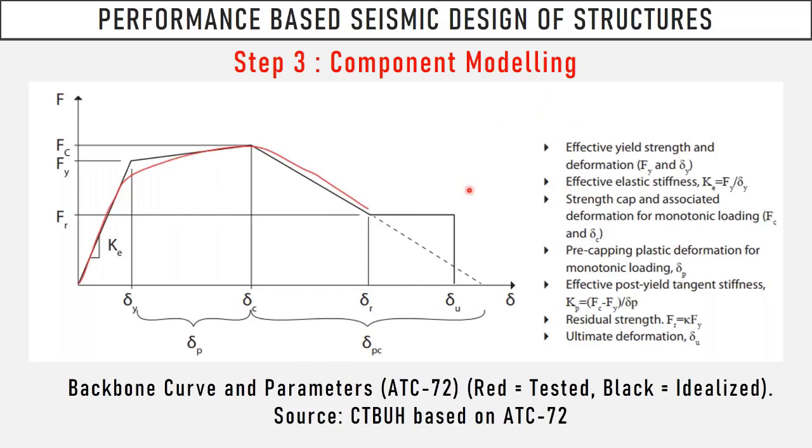Of course, you need a kind of force-deformation relationship. Most of them are based on tests, and since we as engineers don't like to use curved relationships, we make them multilinear relationships.